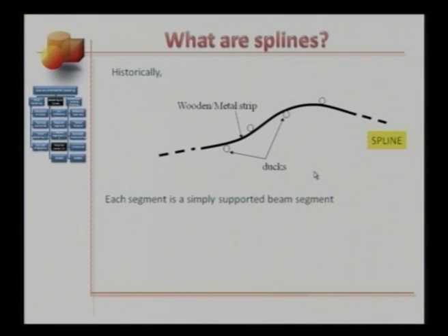You might want to revisit the discussions in your second year solid mechanics course or strength of materials course. Each beam, therefore, will appear like this, simply supported at both ends. Let's try to analyze the structure using Euler-Bernoulli beam theory that assumes small deformation.